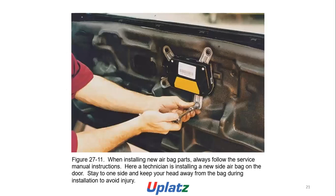When installing new airbag parts, always follow the service manual instructions. Here, a technician is installing a new side airbag on the door. Stay to one side and keep the head away from the airbag during the installation to avoid injury.